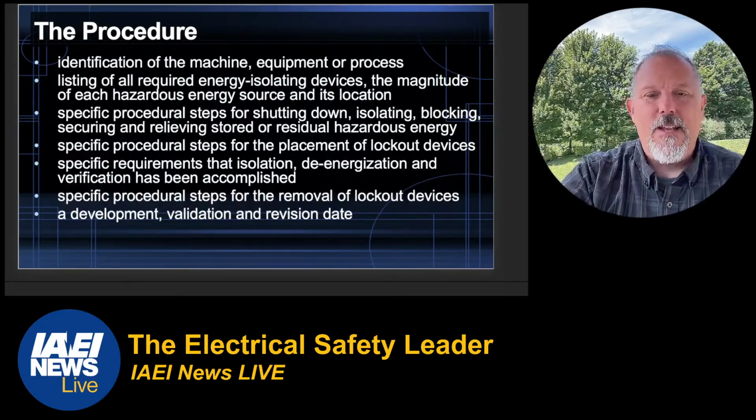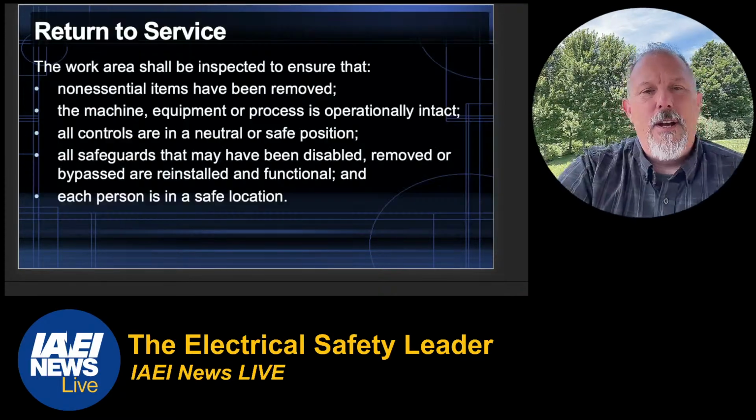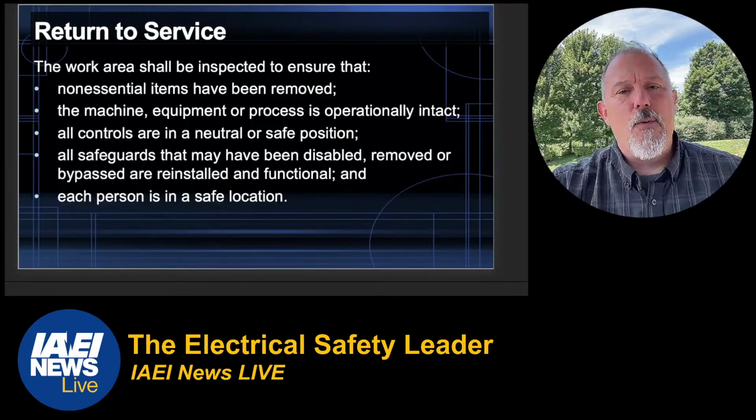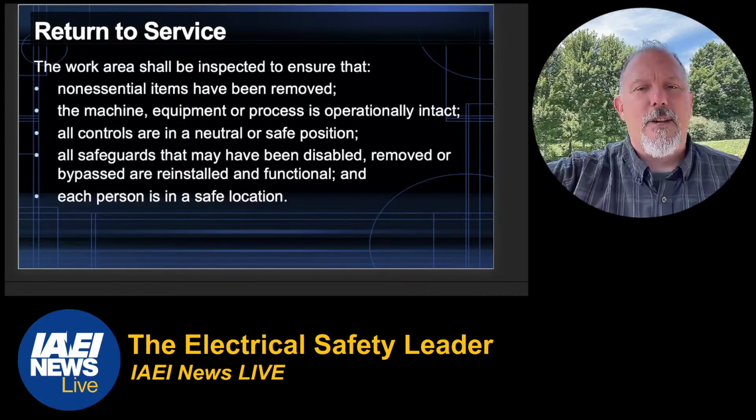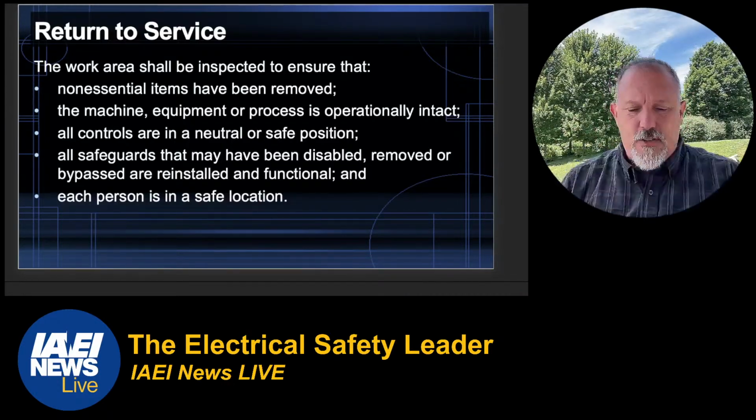Hey, Joseph Violi, thank you for joining in. Lock removal. Here's what I was talking about. The work area shall be inspected to ensure that non-essential items have been removed, the machine, equipment. This is before you return to service.